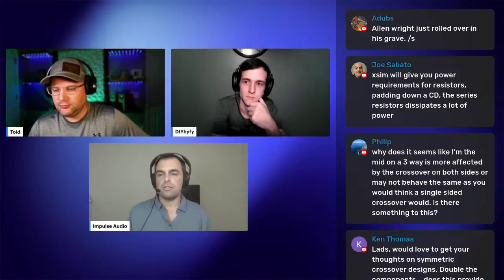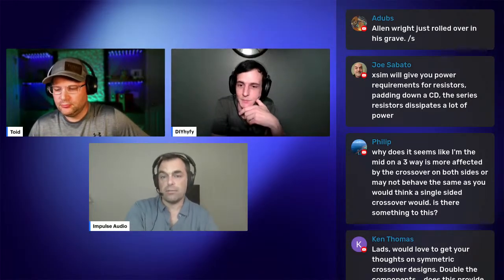If I'm not mistaken, I might be wrong. Ryan, don't you just shut off the phase anyway when you're designing the crossover? No, I'll leave it on. Maybe not at first, but I'll turn it on eventually, because I'll turn it on for the individual drivers, and then I can see, oh, they're 20 degrees out. That's why I'm not getting good summation. It's because the tweeter is leading the woofer or something. So I'm going to do this to the crossover to push it that way and get better summation. But it's not wrong to leave it off. If you're starting out, don't look at the phase. Just ignore it.